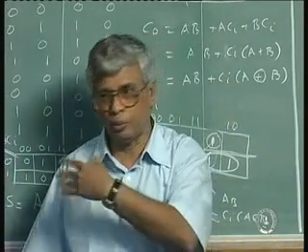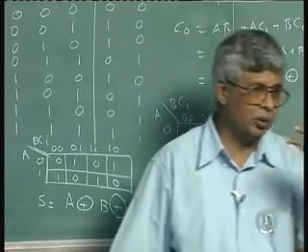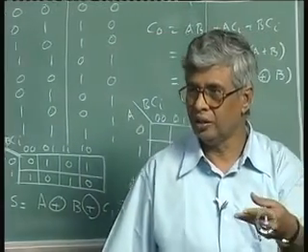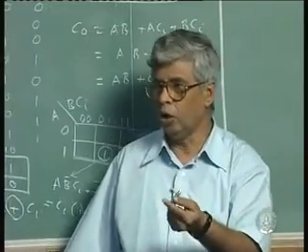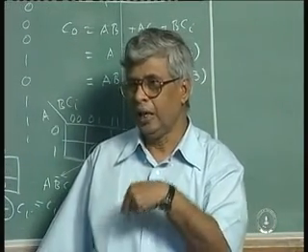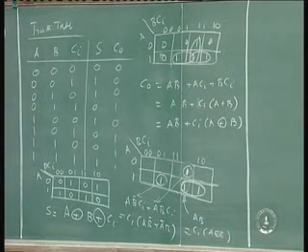You can as well forget about the half adder and do a full adder in which there are 3 inputs, A and B, and the previous carry as the carry input, 2 outputs, sum and carry. Sum is coming in exclusive OR format and carry can come in this format and this format. This is for a single bit.